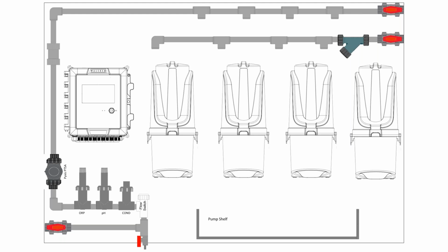That covers our average dosing of our products for scale and corrosion inhibitors, which is around 25 parts per million. In some cases it can be less than that. So running detailed water analyses, looking at scaling, and doing modeling can actually optimize and get you even improved dosage rates.